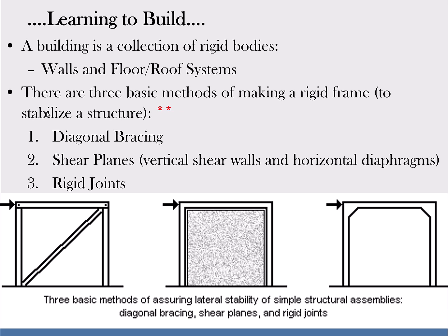With steel, you can weld and make two pieces of steel, a beam and a column, act as one, as if they were one solid piece of material, something that's harder to do with other materials. In some ways it can be done in site cast concrete, or especially if it's suspended slabs. There's ways of joining slabs to walls in pouring concrete. But again, that involves rebar, so it still involves steel.